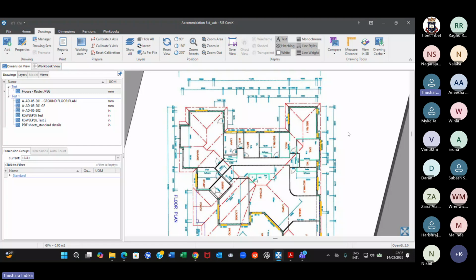But for now, it has to be crystal clear when you create a project. Of course, you can't create a project in here. It's a default project. But when you create a building, your base unit has to be meters, and drawing has to be in millimeters. If you have feet and inches, then your project base unit should be feet, drawing base unit should be inches.